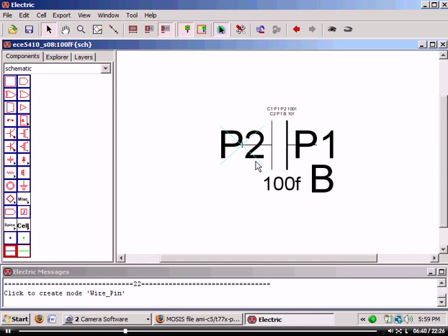Now you all look at it at this point, but what I'm trying to give you is, why would I want to do any of that? I want to give you the tools so that when you go on to an advanced class and you're doing a pipeline A to D converter or something like that, and you ask, how does substrate noise matter? Well, now you know I'm going to tie all my substrates and my capacitors or my nodes to some value, and then I can put noise on that value, and I can see how the behavior of the data converter changes. We don't need to worry about this. We're doing digital. Life is good.